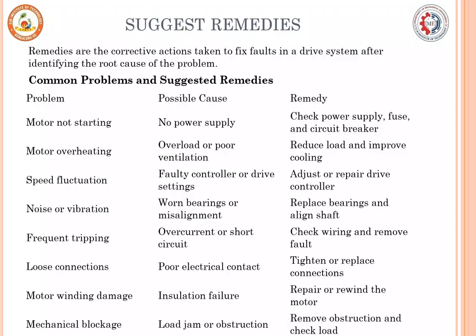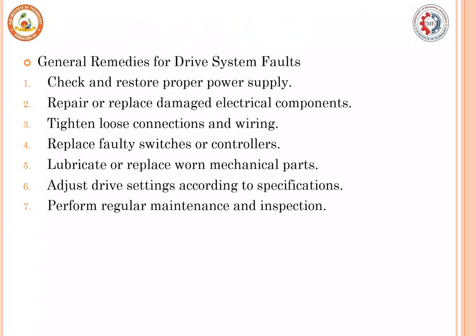Motor winding damage means there is insulation failure, which is a possible cause. The remedy is to repair or rewind the motor. Mechanical blockage: load jam or obstruction. Remove the obstruction and check the load. So these are the general remedies for drive system faults.